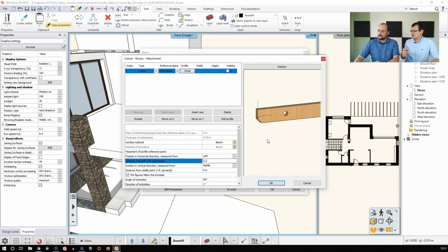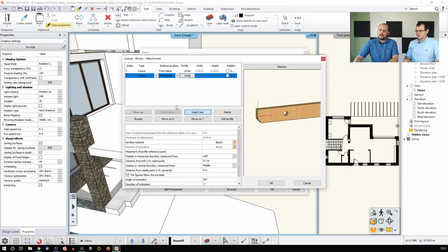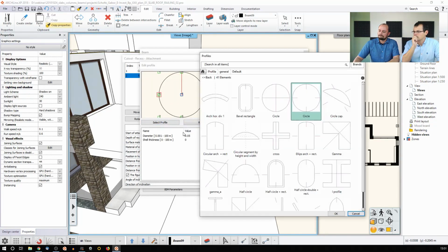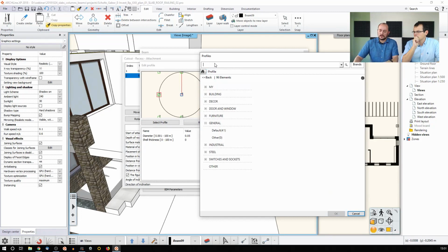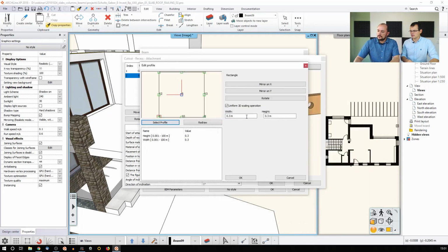What about attachments? I saw something about adding attachments to it. Well, you can use an attachment. I will just change it now. So it's now just added on. But I could add an extra, just the same way. I will add the recess because I think this is something that I should position over here, and this should be, instead of a circle with the same settings, a rectangle. Let's just go to the properties and find a rectangle. And this rectangle should be 0.1 by 0.1.